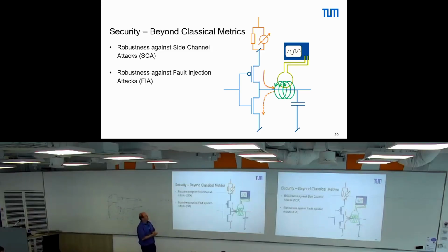Then one last thing that I need to mention, because I'm a hardware security guy. What is also important for us are things like the security of a circuit. We do not talk about this here in the lecture, but one problem we have is this dynamic power consumption. Our circuit switches. If the bits flip, then we have a current flowing here, and we can measure effectively the power consumption at the VDD or from an EM emanation.